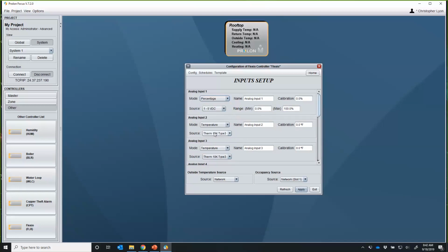is scalable. Okay, well, why would I want anything other than 0 to 100%? Well, the thought process on this was having accessibility to LEL sensors, propane, natural gas. Full scale on a lot of these transducers is 0 to 50%. So that way I can show this as propane LEL and it's going to display a range of 0 to 50% across the full signal. We don't want someone thinking, oh, I've got 100%, we're about to explode. So that's why we can scale that.